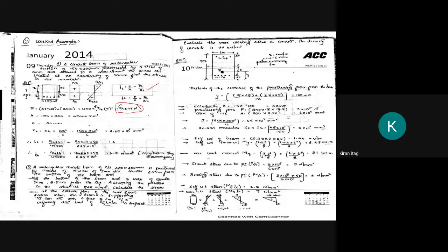As this is a symmetric rectangular section, the stress at the top and the stress at the bottom will be the same. You know that for a rectangular section, the moment of inertia, you have already learned, I equals BD cube by 12. Correct? You have two options: Z can be calculated by I upon Y. One thing you can calculate I, substitute here, and the Y value will be the neutral axis, that is 150 mm.